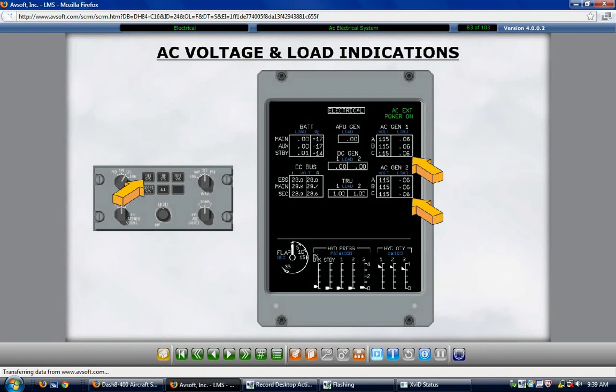The systems and components requiring the 115 volt variable AC power are: 1. The de-icing and anti-icing heaters, 2. The standby hydraulic pump, a backup for the number 1 hydraulic system, 3. 2 transformer rectifier units, and 4. The number 1 and 2 auxiliary fuel pumps.